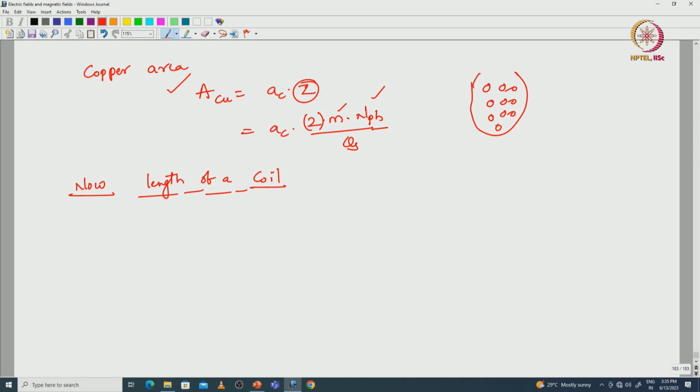In order to find the length of each coil, we can see here the stator core. What we have to know is the length of the stator core. We have to place the coils, right. We have done how many slots are required, what type of winding, how many turns each coil consists of, and SWG data for each conductor. The remaining thing is how to calculate the length of coil, resistance of the coil, volume of the copper and weight of the copper.